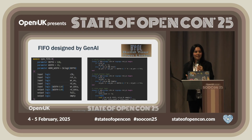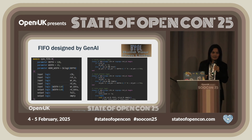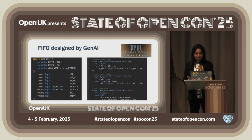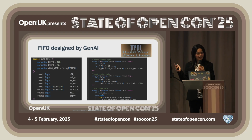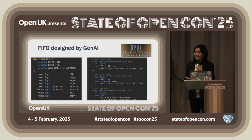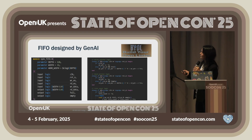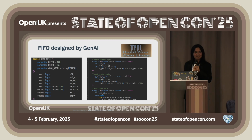Let me walk you through a couple of experiments that we have done, and show a couple of examples on how we can supercharge chip development using your GenAI assistants. As a hardware engineer, this is where we start. I asked a copilot to create code for this block, in this case a FIFO. It has done a pretty good job: here is your module, a synchronous FIFO, with all the RTL that goes into it. So far, so good. It has done a very decent job.